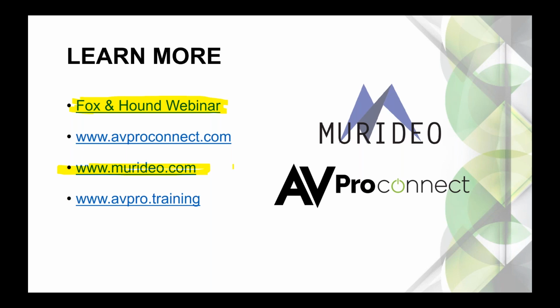So you don't see the chroma subsampling, you don't see the bit depth. You do see that on some high-end sources, but the only one I'm aware of now is the high-end Oppos. They'll show you native format of the disk and then output format of the device, and chroma subsampling and bit depth combined. So again, what I say is test. If you don't have Fox and Hound, use the info button or see if the TV physically puts HDR on the screen like a logo. Those are the ways to test it.